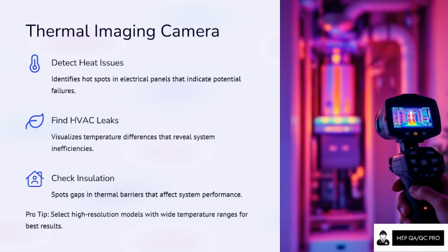Yes, through the camera you can also identify the leakage of air, when there is less air in any space. So you can identify through the thermal imaging camera whether the system has any leakage in the air, or any leakage in the duct, or any issues in the FCU, so that from there you can easily identify the leak.